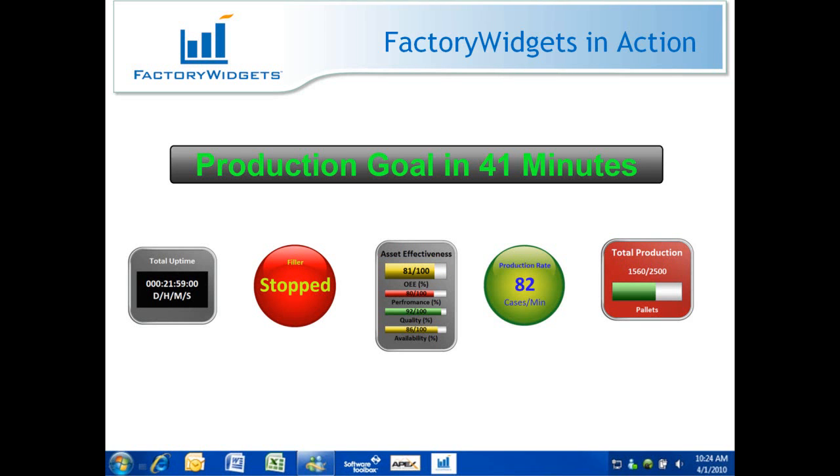At the top is the reader board, and it can display multiple messages with variable information. Customers like to use them on the plant floor on large screen displays. On the lower left is the timer, and it can be used for such things as measuring up or down time, changeover time, or time in a process step. The next factory widget to the right is the discrete orb, and it can show the on or off state of an asset in the manufacturing system. In the center is the KPI factory widget. The KPI can display up to 4 metrics and their progress towards targets. To the right of center is the analog orb. It displays the value of the data being monitored as well as changes its color based upon that value.